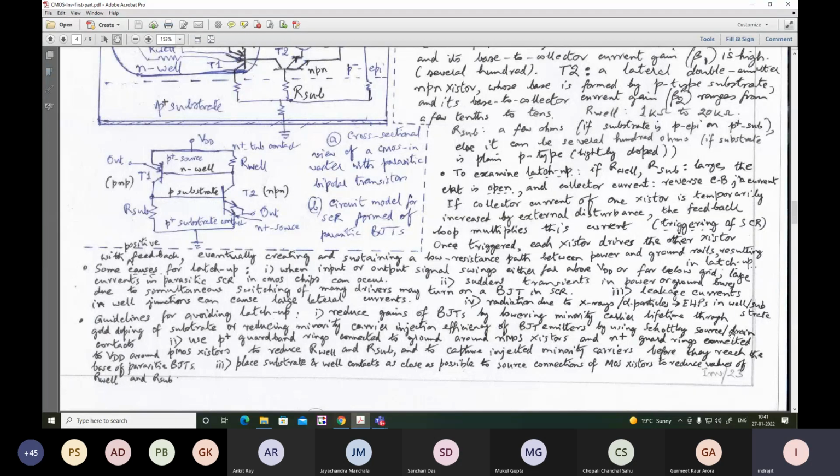The Schottky barrier hardly allows the transistor to go into saturation. Its operation is restricted to the active region and cutoff. Scarcely ever do they go to saturation, so that the current will be limited.